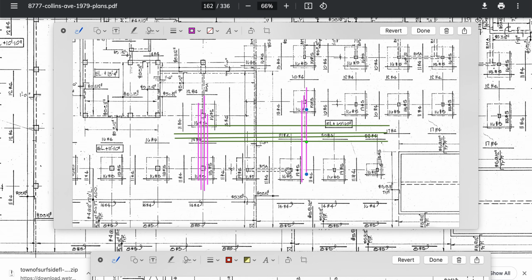So imagine the steel here now coming across, having to take on this load of the steel coming this direction because it's not landing on a column. So now any loads here, the dead loads, all start adding up. Now you have to start calculating all these dead loads, all that concrete, the pavers, not the human load. It's so insignificant at this point. I don't imagine this deck having big pool parties, 80-year-olds coming out there jamming and partying and dancing all night, slamming and bouncing on the deck. Very possible, but we just discount them. Let's just go to dead loads only.